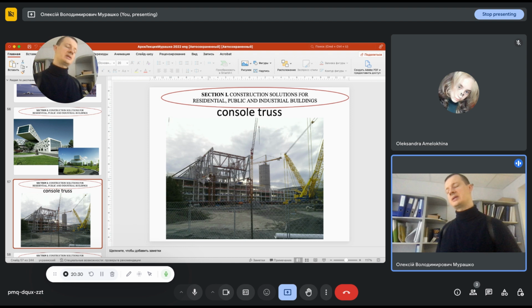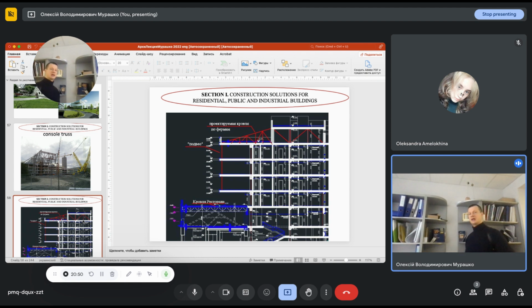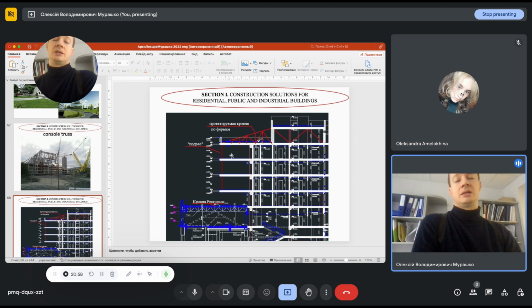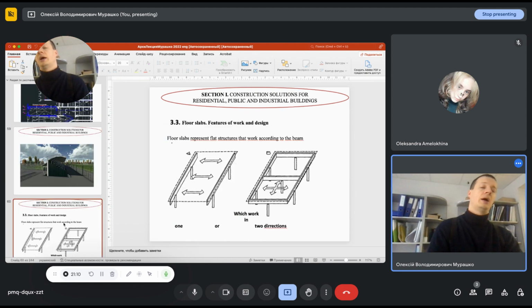Here is how it was built. You can see those truss elements, which serve this building as load bearing elements, and those trusses are supported by the columns which you can see over here. Such a situation you can find in a solution like this. It also gives an ability to redistribute this moment and make a huge cantilever by adding such elements and such trusses to redistribute internal forces. Some more solutions.